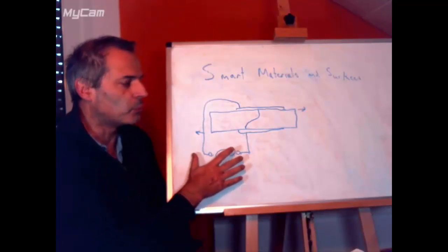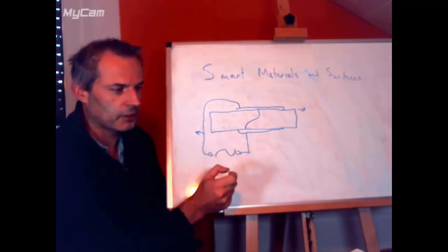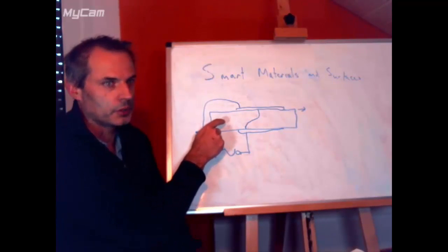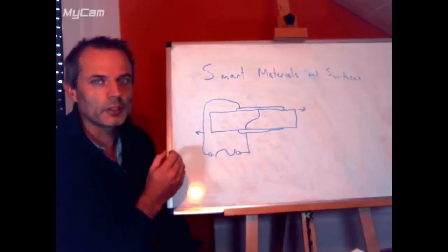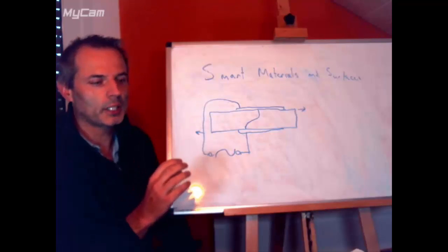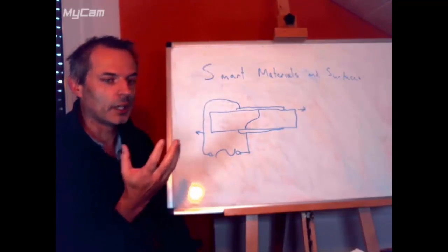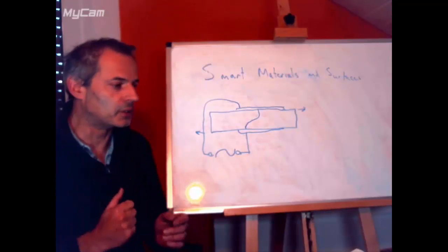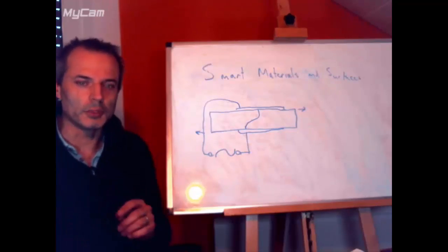So they have a wider band of resonance than the quartz, and the quartz narrows the band and fixes it to what it wants to do. Quartz, in this case, as a piezoelectric material and as a resonator, is particularly good at fixing the resonance, which is why we use it in watches and computers to determine the time. Also in many other cases where we want a time signal.